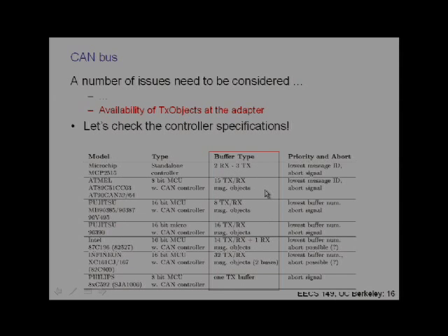So if you're an engineer who's using CAN, you have to think about, okay, for my implementation, let's say I have this Infineon microcontroller with the CAN adapter. How many buffer spaces do I have? Okay, it says in the spec sheet there's 32 spaces, right? And depending on that, you'd have to compute the corresponding response time. Okay, so let's assume a rather pathological case where the adapter only has a single buffer space.